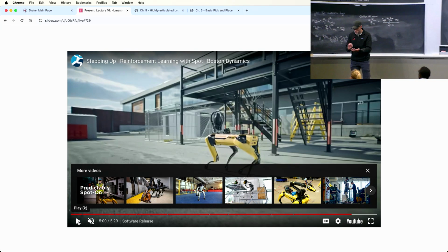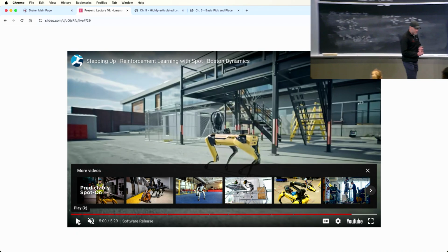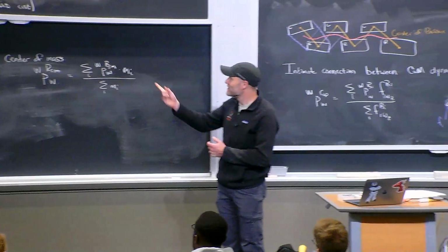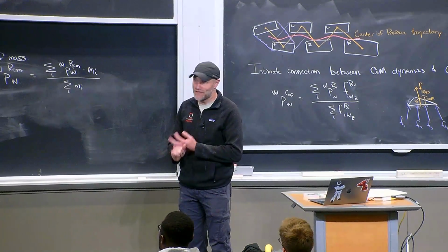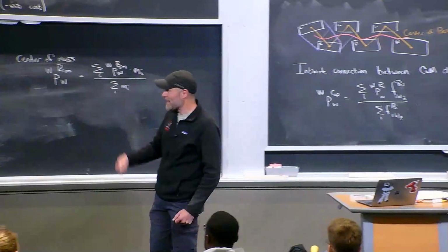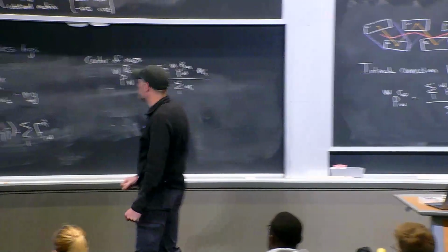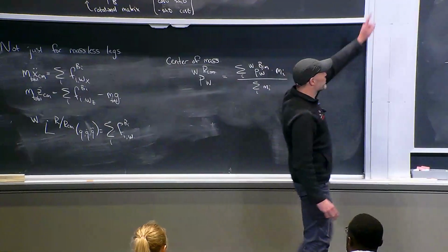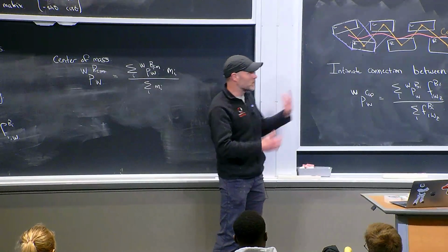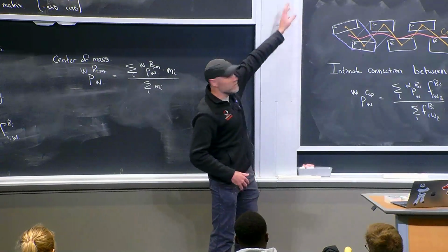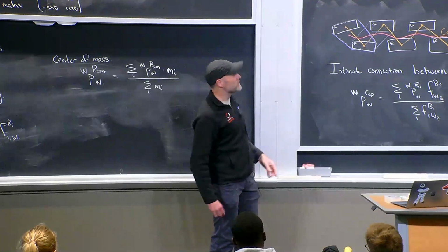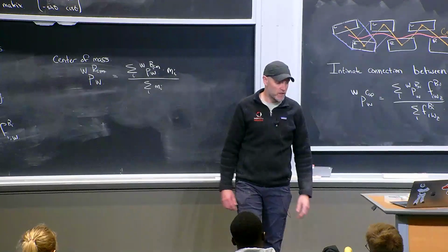Okay, so high level, when you have enough degrees of freedom, things get easy again. And there's a pretty good recipe in the zero moment point, and you can actually push out on that and, I think, relax a lot of the assumptions. And that's what people have done: slowly, instead of separating out footstep planning and center of mass and joint angles, they're finding ways, like in Atlas, to jointly plan all of them, okay? And we'll talk about the optimization way to do the discrete plus continuous one in one of the next lectures.